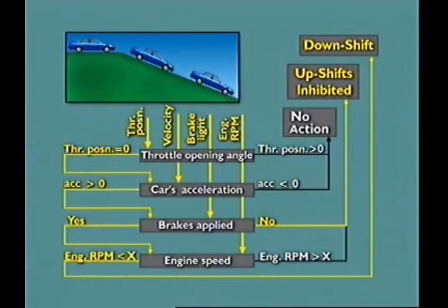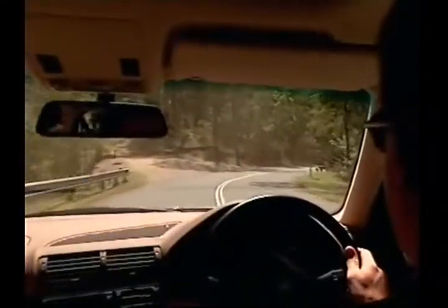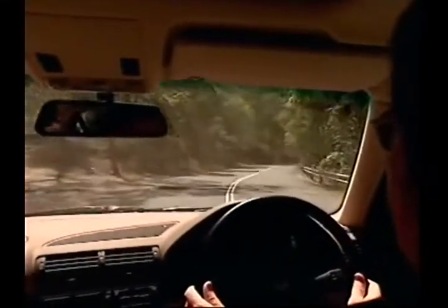Downshift only occurs below a preset engine speed. This avoids application of peak engine braking torque. The downhill identification gradient mode becomes inactive once the accelerator is depressed again.